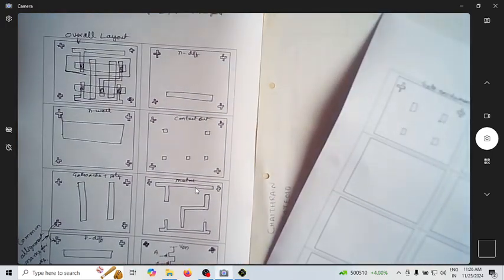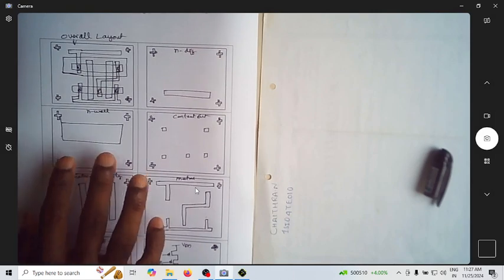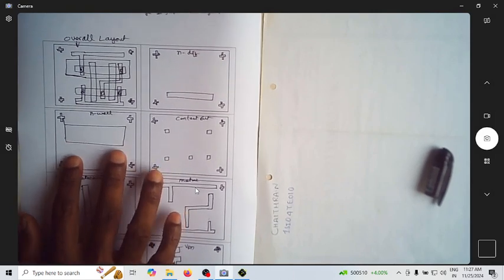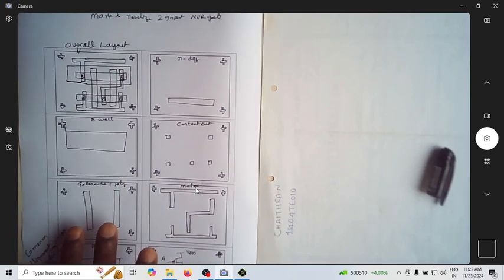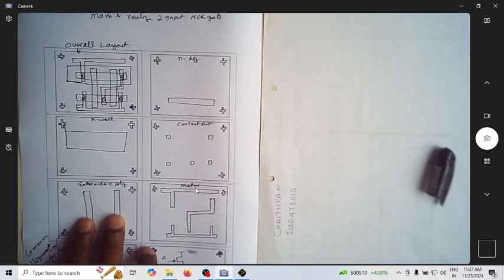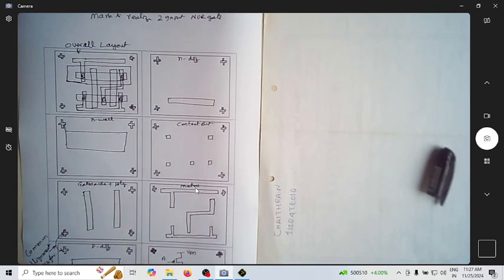Interestingly, what we are trying to show here is the common alignment mark for all the masks, and while writing these masks, of course, they have to be to scale, so they should be perfectly aligned with each other, so that you can end up with the realization of this two input NOR gate structure. Similarly, you can try out any other logic for that matter. It need not be an AND gate or NOR gate.